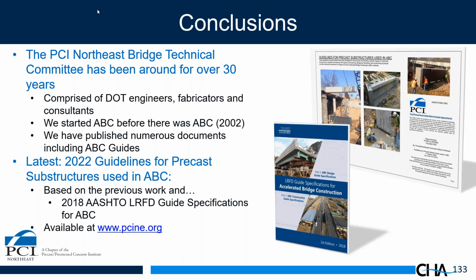What are the major design differences between precast and cast-in-place connections? I love this question. I do a lot of talking, as you can imagine. I go around the country and I always ask the question, say for a precast pier, I'll ask everybody in the audience, raise your hand if you know how to design a cast-in-place pier. And they all raise their hand. And my response is, congratulations, you now know how to design a precast pier. Really, the design is the same.